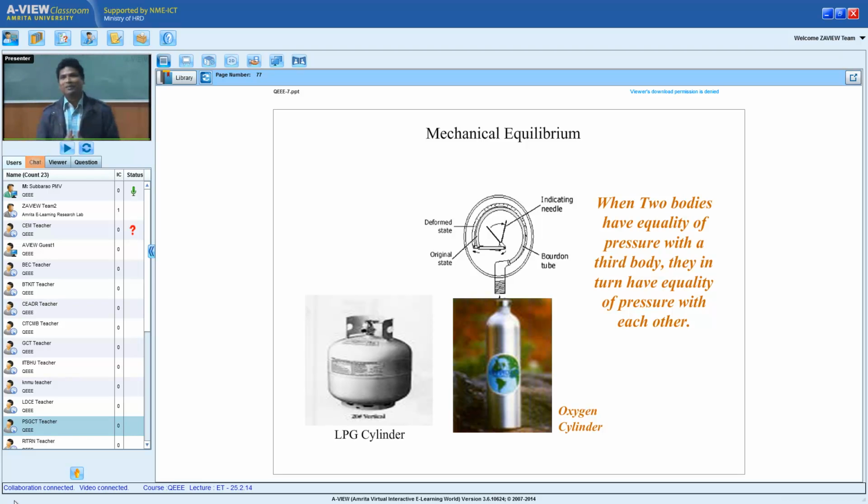When it comes to thermal equilibrium, the only thing which is common is temperature. If I take 100 different thermal equilibriums, all of them talk about the equality of temperature. But when I say mechanical equilibrium, sometimes pressure is the same. Sometimes force is the same, where you cannot even define pressure. Sometimes in a rotational system, the torque is the same. But all are mechanical equilibrium. So that's how the zeroth law talks about thermal equilibrium and leaves it to our intelligence to talk about other equilibriums.